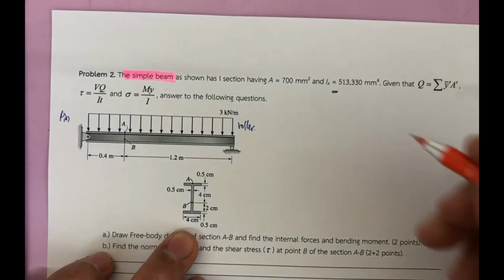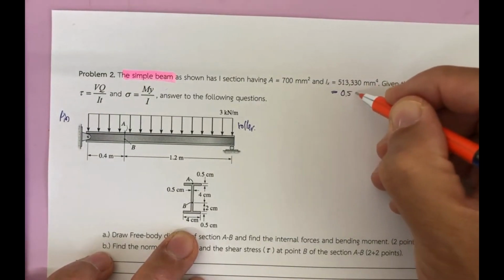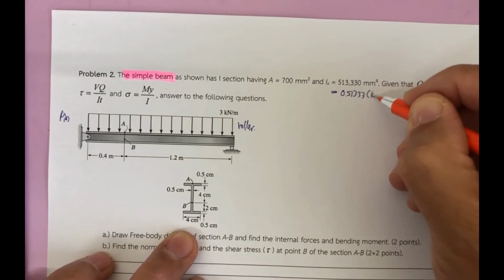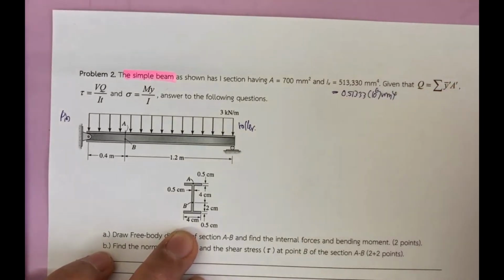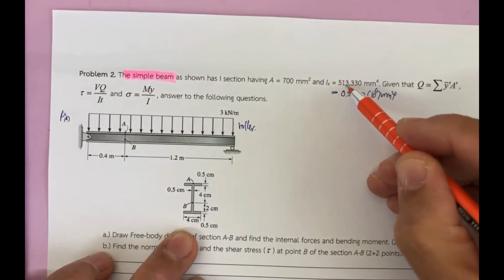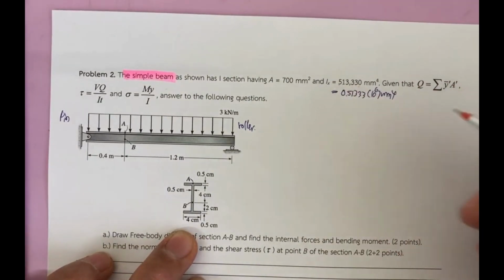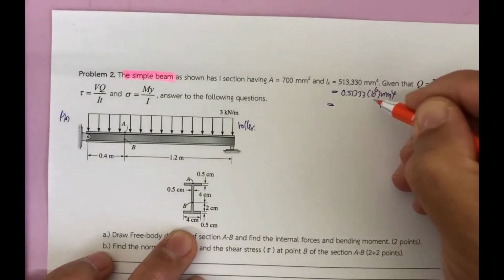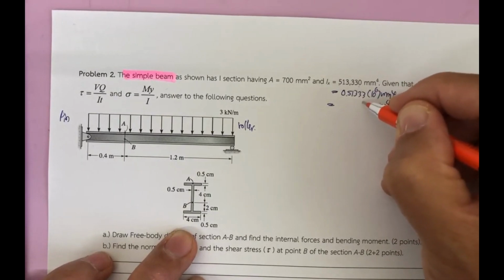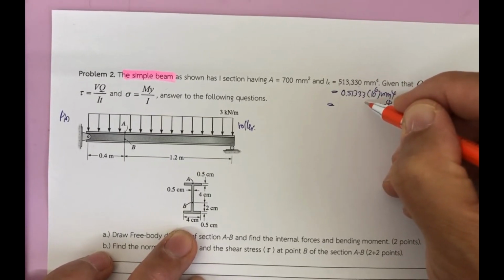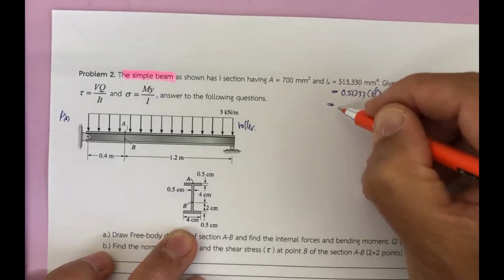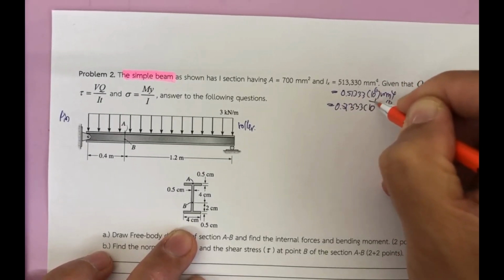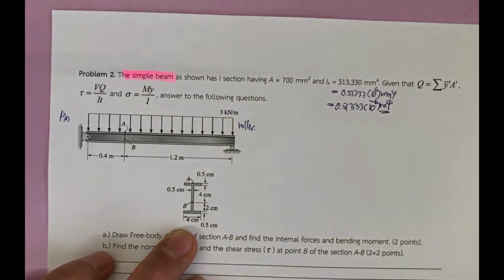If you would also like to have this in meter to the power 4, that means you're going to have this one, let's say, 10 power 6 millimeter to the power 4. 1, 2, 3, 4, 5, 6. Okay. And if you like to make it meter to the power 4, you have to divide this one by 10 power 12. The factor of 10 power 12 comes from what? You know that, right? Okay, that is going to be 333 times 10 to the minus 6 in meter to the power 4.